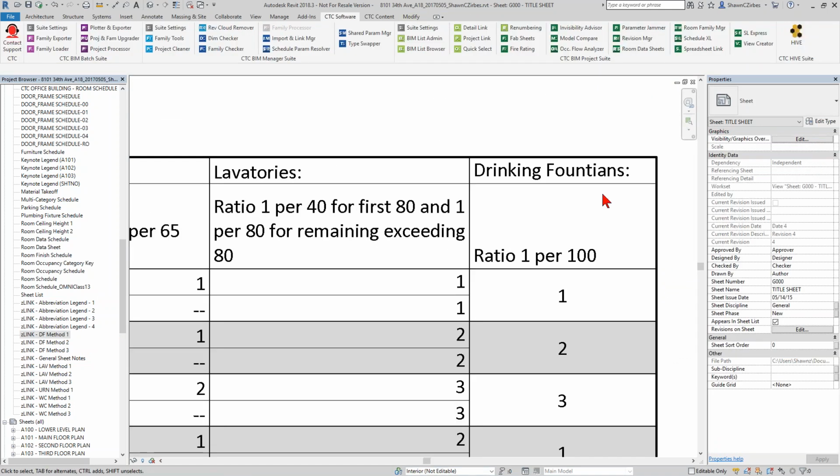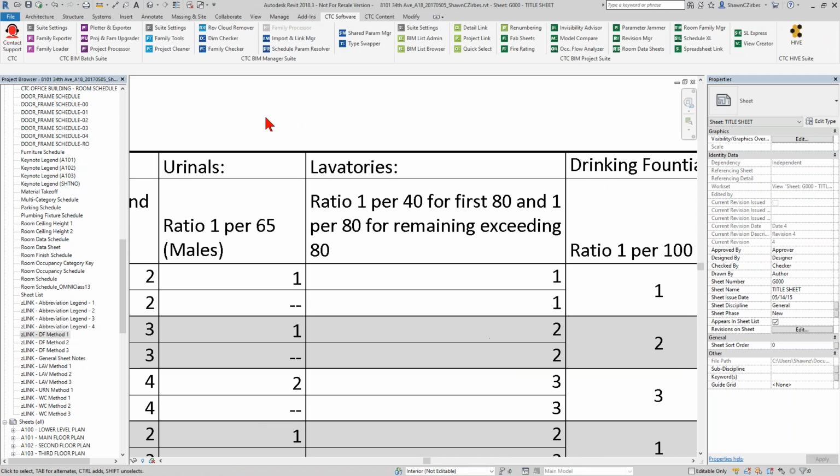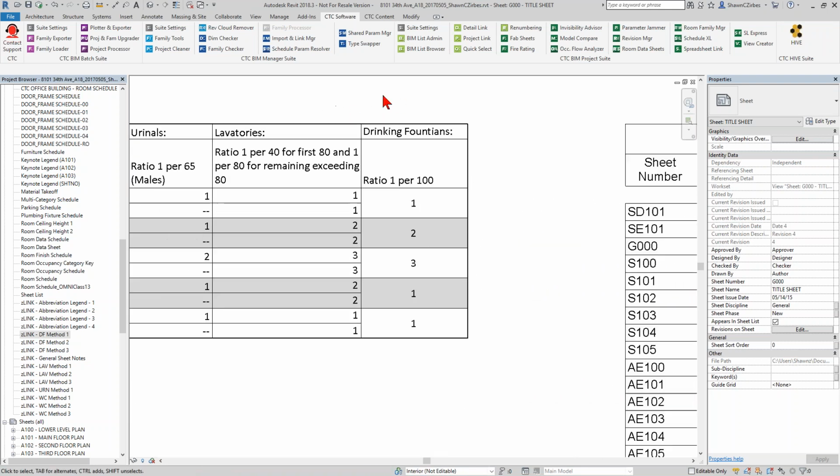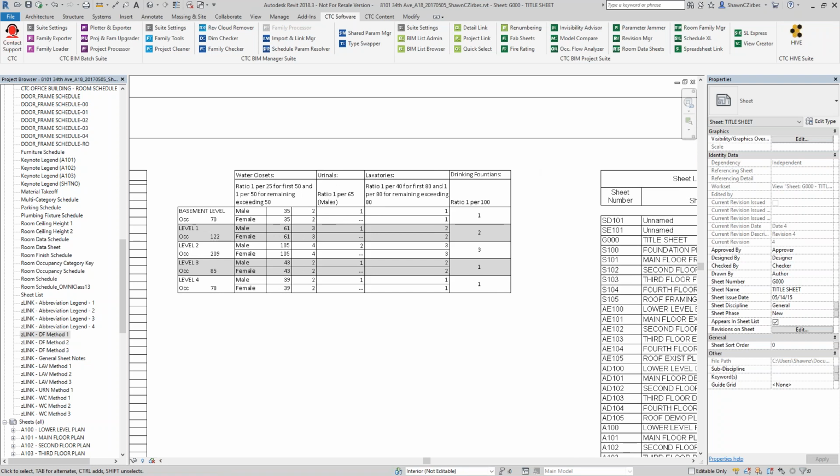And the way that I built these up, because I was mixing and matching these, I put intentional line weights on different parts of these tables so that when it stacks all together, it looks like one continuous schedule. You can do some pretty interesting things when you start working with Excel in creative ways and by using Schedule Excel to bring that content in.